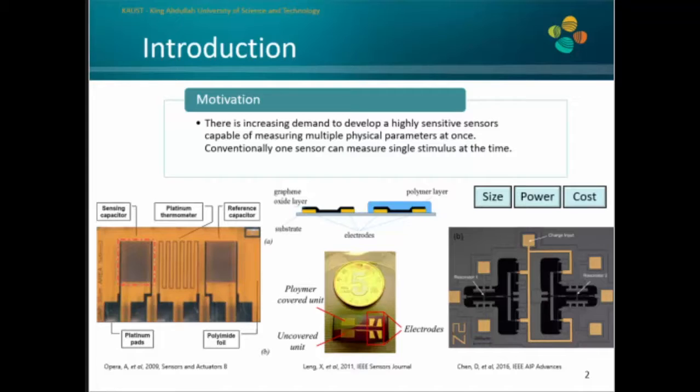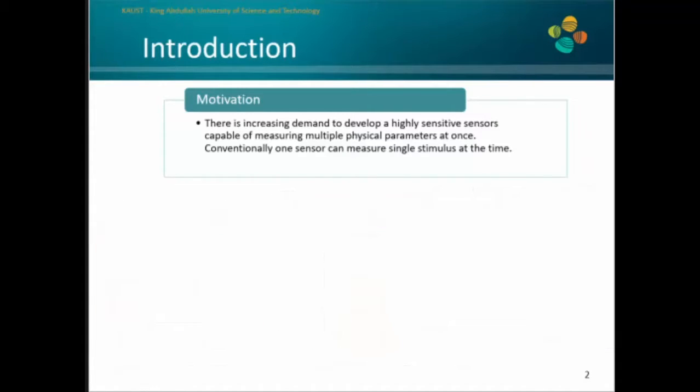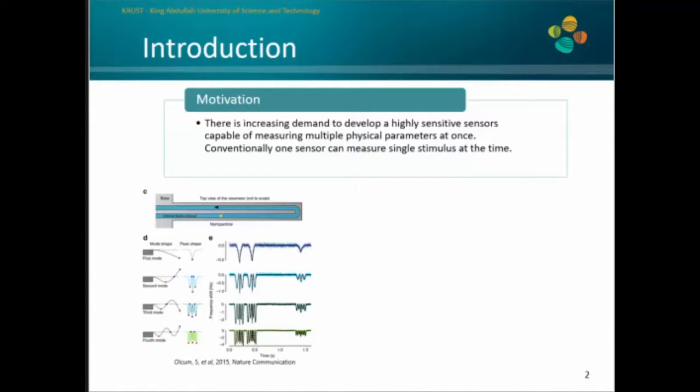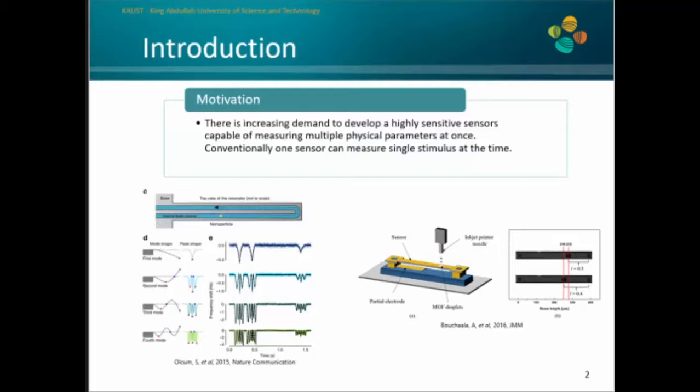Recently, in resonator-based sensors and applications, the different modes of vibration started to attract attention, where researchers started to think of each mode of vibration as a different channel for sending information. For example, here, in order to determine the position, the velocity, and mass of a moving particle inside a microcantilever resonator, we need to rely on the four modes. In our previous work, we showed that using two modes of vibration, we can determine the position and the amount of mass on the resonator surface.